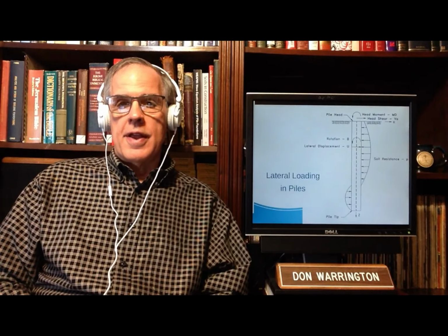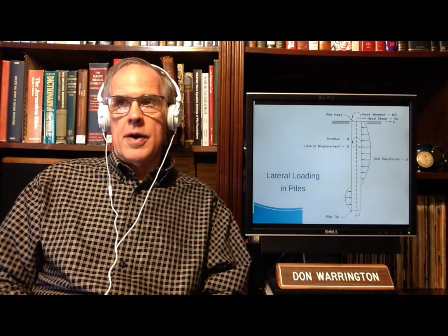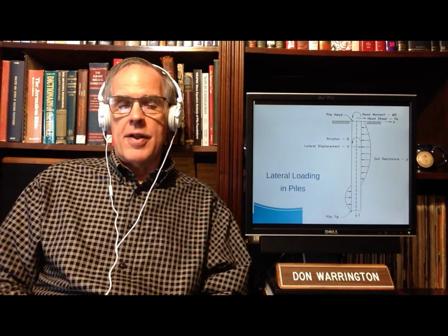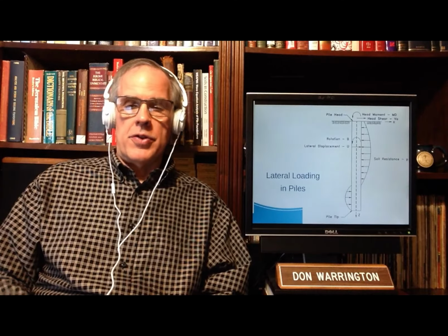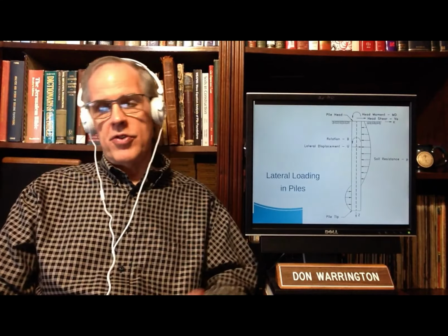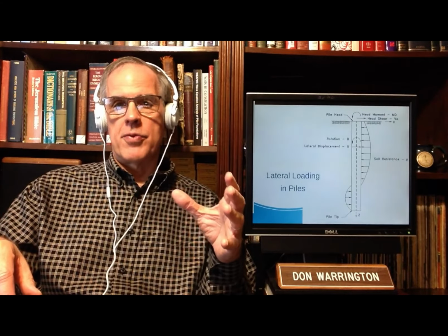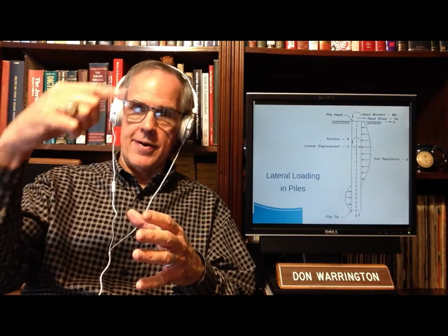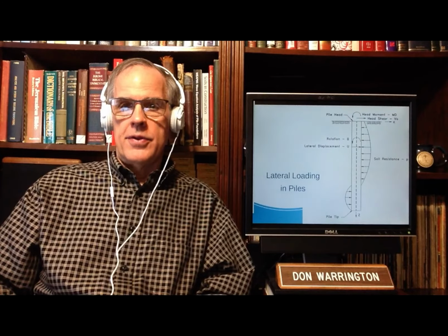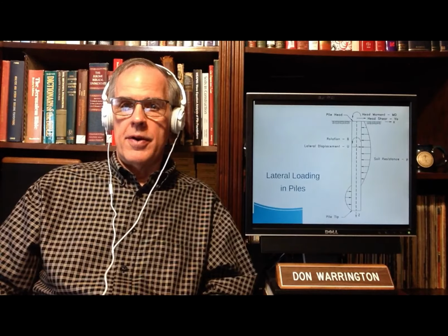The loading is at the head of the pile and the resistance is below that, as opposed to sheet piling, which is kind of the opposite, where the loading is all along the wall, and the resistance is split between the passive forces down here and the anchor up here in an anchored wall. So there are important differences, but there are important similarities as well.